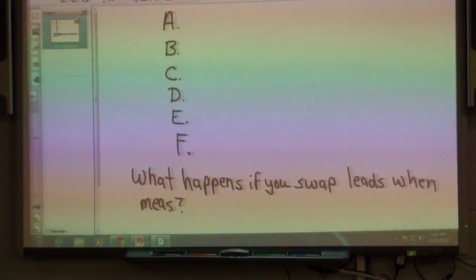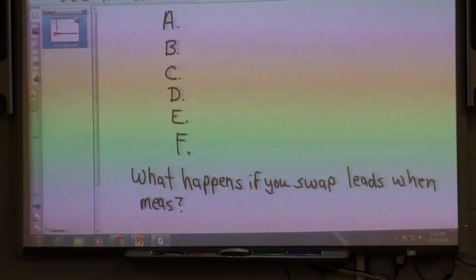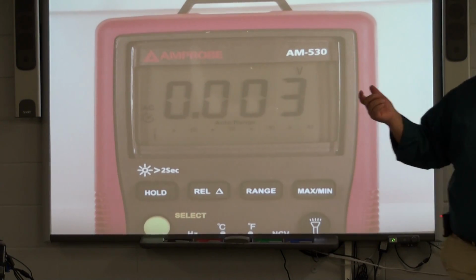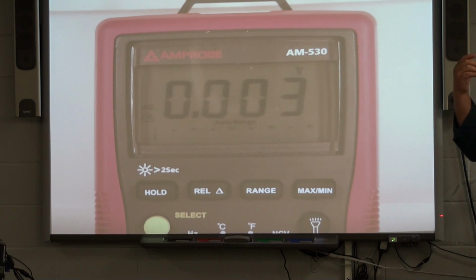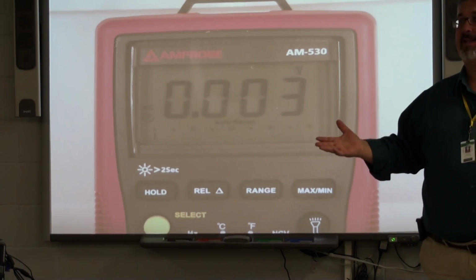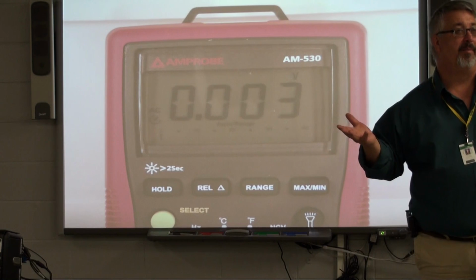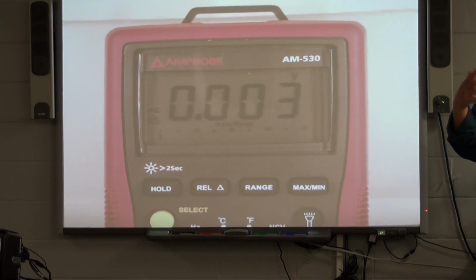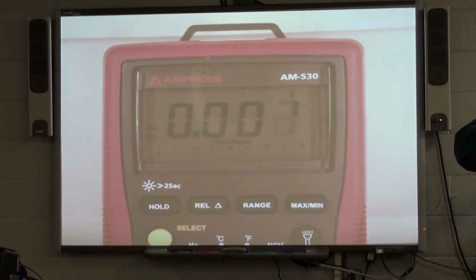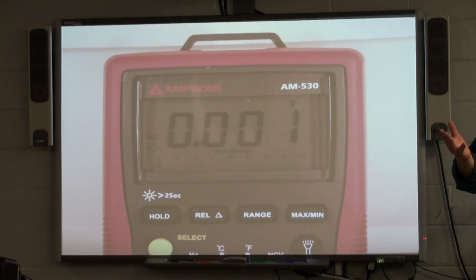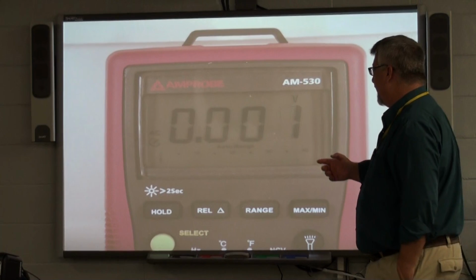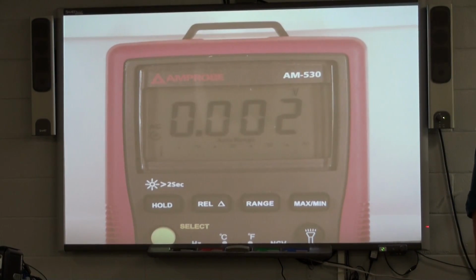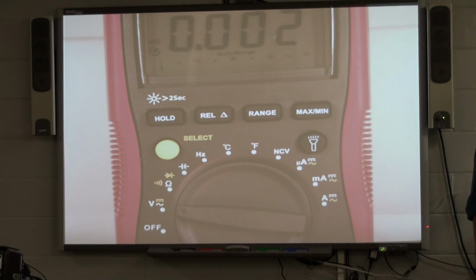You'll be bringing a piece of paper with you. So I need both of these Amprobe meters and the Klein meters, and I'll bring the Klein up here in just a moment. They start out in AC, and that's because they're electrician meters. And 9 times out of 10, as an electrician, you'll be measuring AC above DC. So we have to change them from AC to DC. And I'm in the volt selection. I'll slide that up just a little bit so you can see.